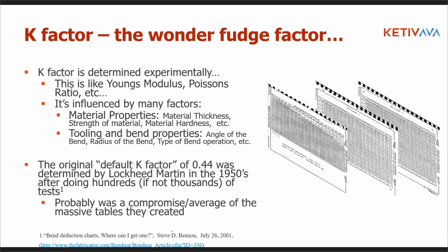So how much you're actually bending. What's the radius of the bend? What is the type of bend operation? Is it a brake press? Is it an open air bend? Is it a die? Those can all influence what the actual fudge factor really is.